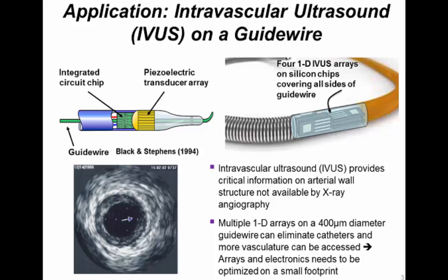It means we need a high frequency, high bandwidth front-end circuitry, which doesn't allow that much design margin. In addition to that, we can't put that much adjustability because, for example, if you want to change the bias of the amplifier, you need an extra interconnection and an extra pad, which is directly related to the increasing of the size. So in the designing phase, we have to accurately simulate the front end and the CMUT.